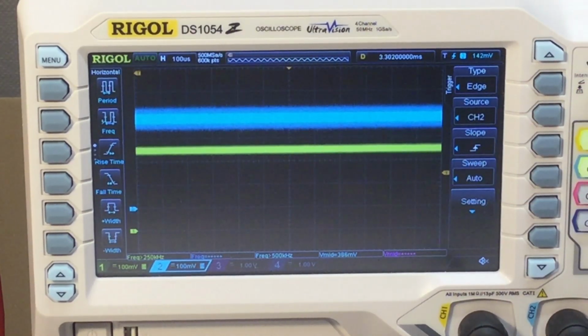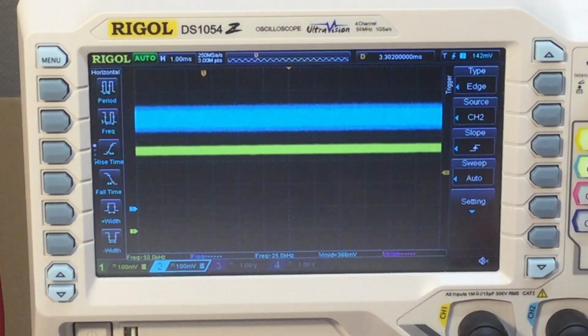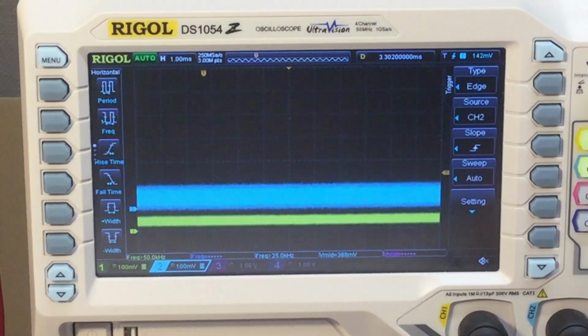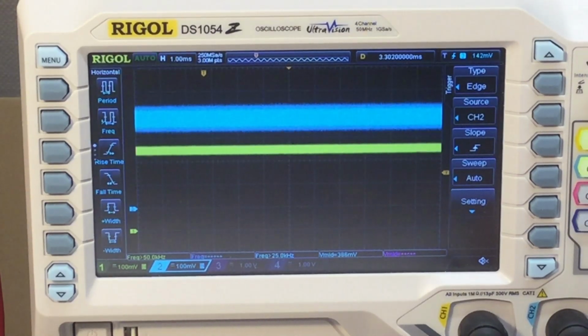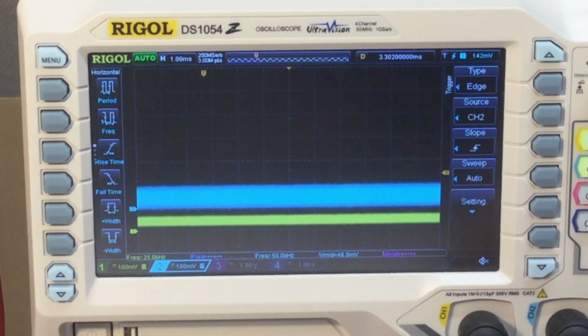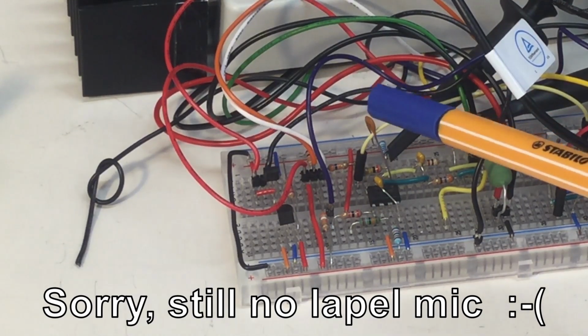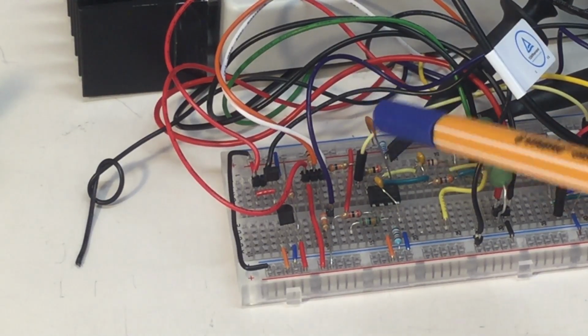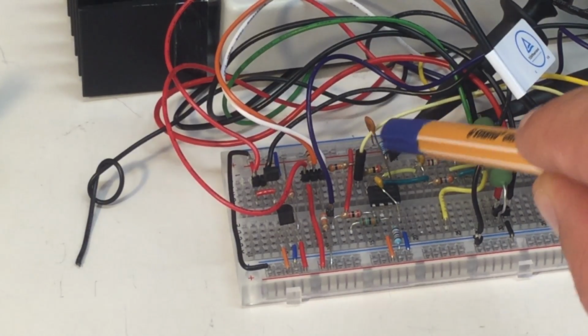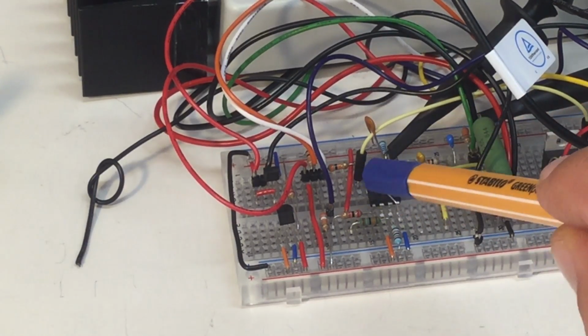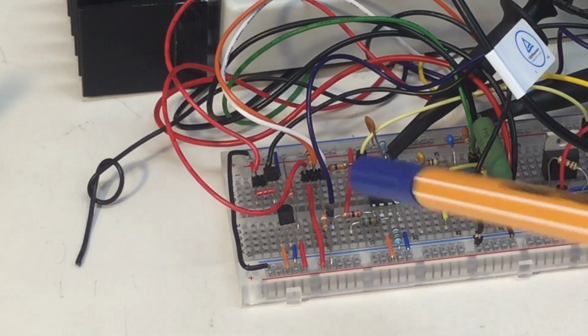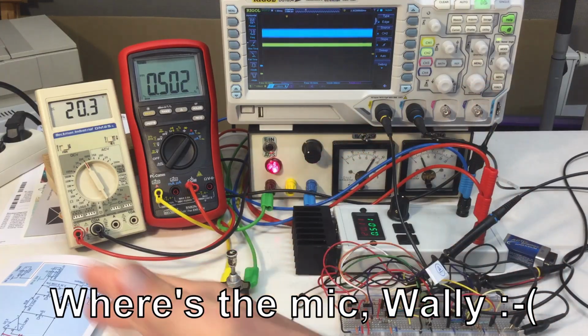The same in real time. Let me change the time base. 1 millisecond, and I'm flipping the range switch. That's how it should work. That's the 10 nanofarad I lopped in here parallel to R5. That's here, just after R4. Because that works so nicely.